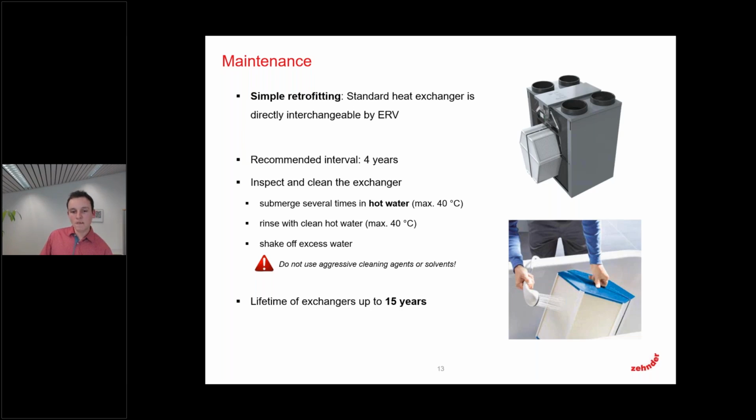For this procedure, please do not use aggressive cleaning agents or solvents, because they could damage the membrane. The lifetime of the heat exchangers depends on the local conditions and how well you did the inspecting and cleaning, but in general, we say that they have a lifetime of up to 15 years.